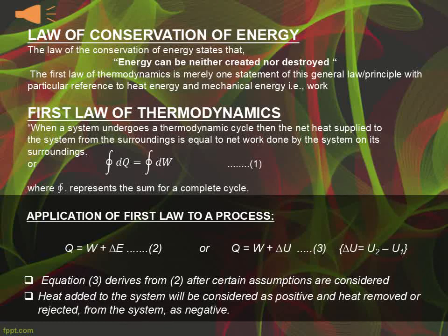Generally, when heat is added to a system, its temperature rises and external work is performed due to increase in the volume. The rise in temperature is an indication of increase of internal energy. Therefore, heat added to the system will be considered as positive and the heat removed or rejected from the system will be considered as negative.